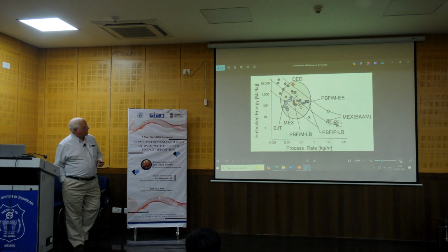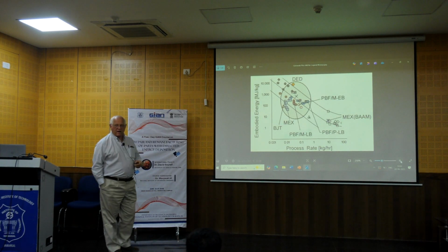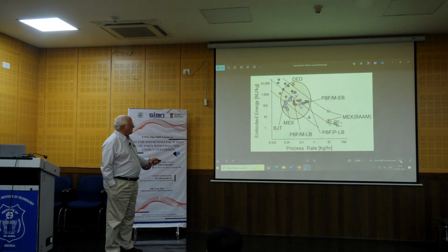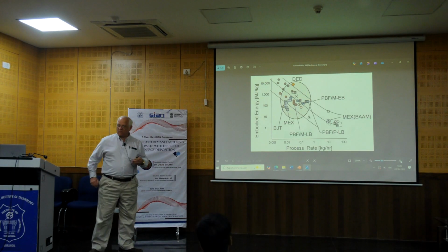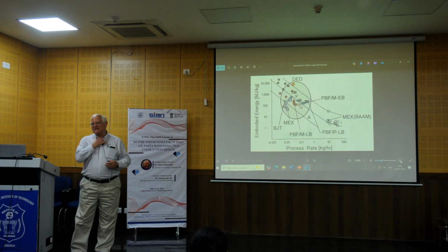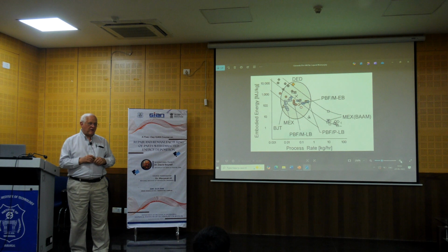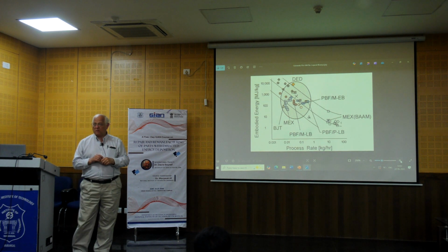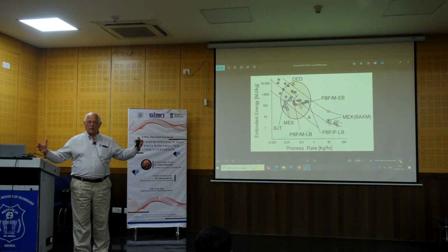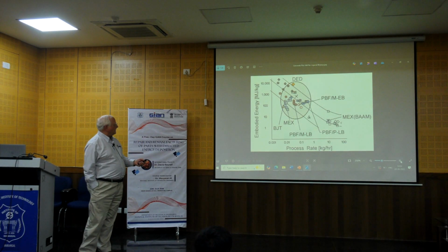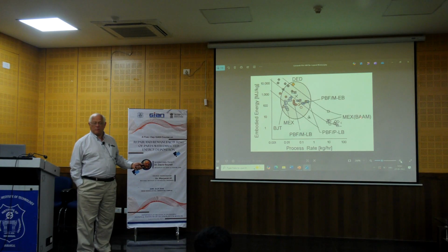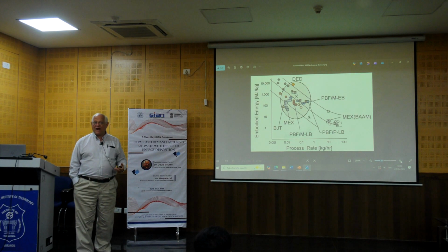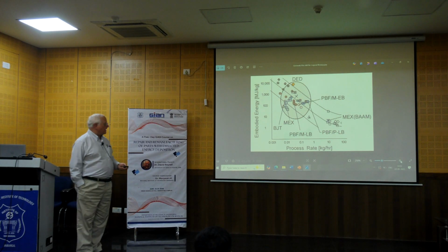So what we see here, I sort of zeroed in on those processes. Material extrusion, the so-called BAAM process, was developed in Tennessee. It's big area additive manufacturing. It's just massive deposition of polymer to create large structures, and it has a very high build rate. You can see here, we're talking 10 kilograms per hour being deposited.